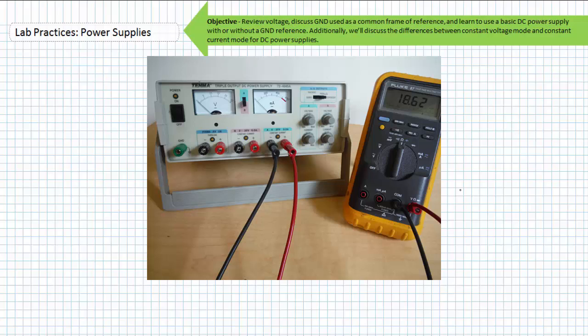I know a lot of material is hitting you at once, but eventually, strictly through repetitive exposure and me repetitively hammering you with a function, leads, range, and placement checklist every time you use the DMM, your lab is going to go this well too. The ability to quickly, flawlessly and safely transition from voltage, resistance, and current measurements using common instruments like the DMM is the primary skill you must develop during a supporting hardware lab.